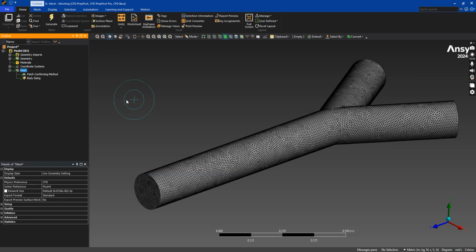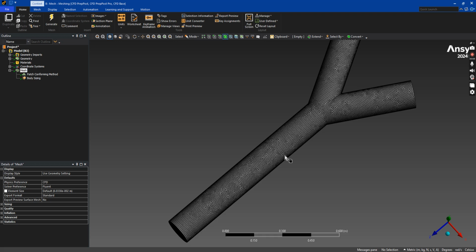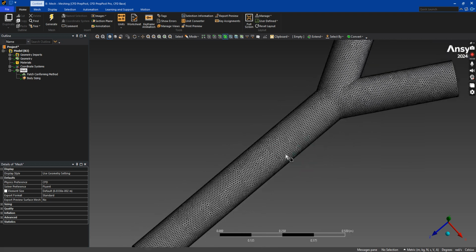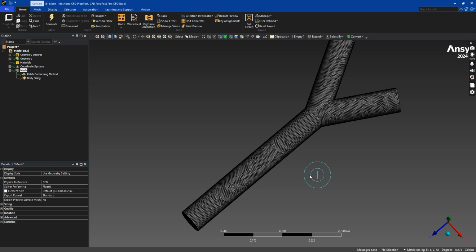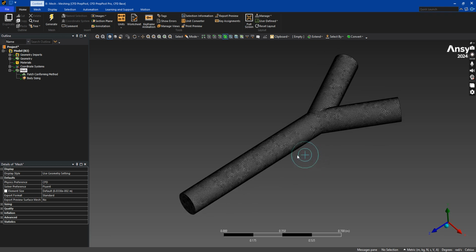And if we look at the meshing, you see a much finer mesh. And now, as we have seen previously in the laminar pipe flow or in the 90-degree bend flow, the edges that the flow matters is very important while you are doing a meshing.